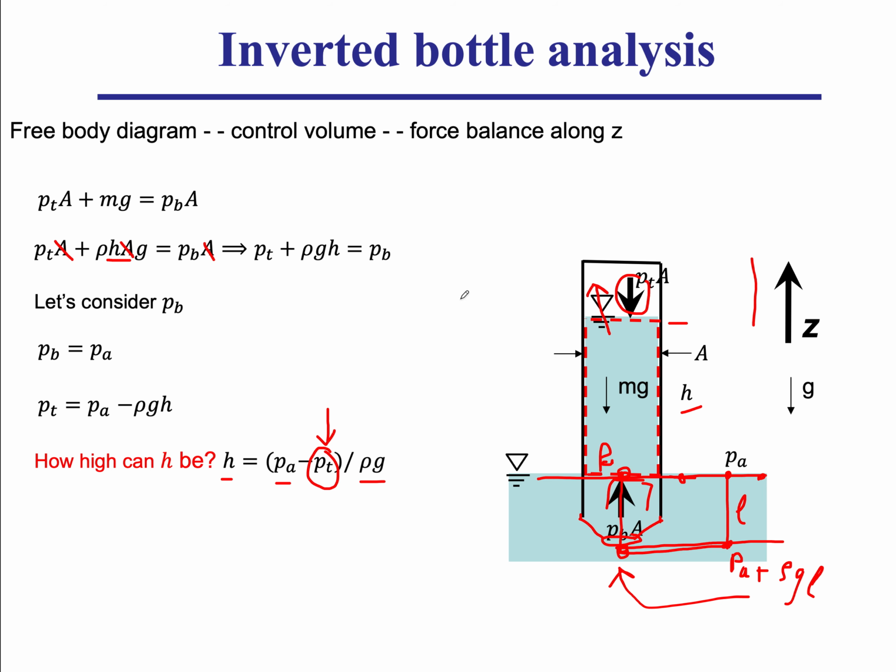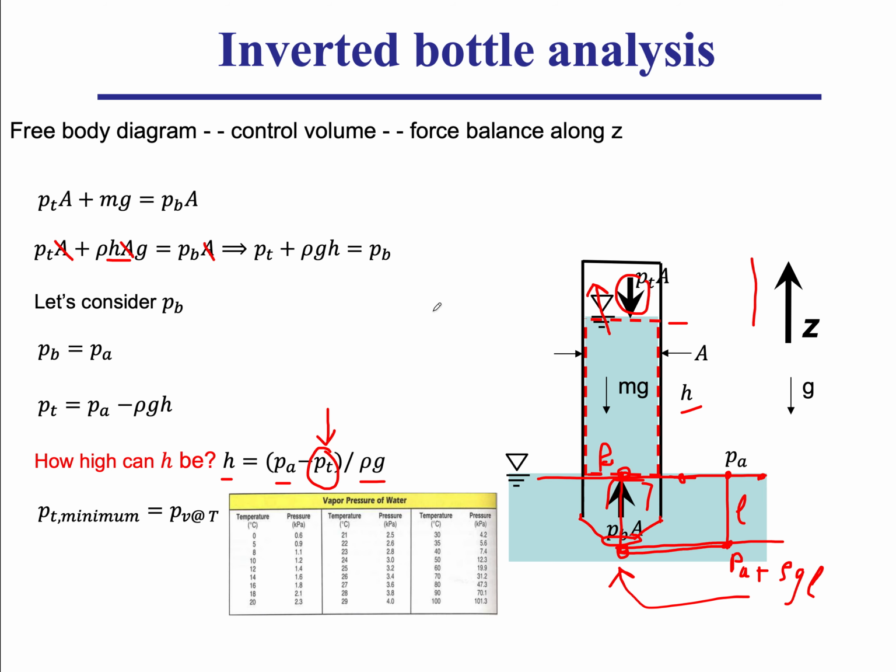And can we get what this water vapor pressure is? Of course, you go to your thermodynamic tables and find the room temperature and you get the vapor pressure at that room temperature. So if I am at 25 degrees C, I'm going to get 3.2 kilopascal. So when you're at sea level at 100 kilopascal, your water boils, so it transforms from liquid to gas.